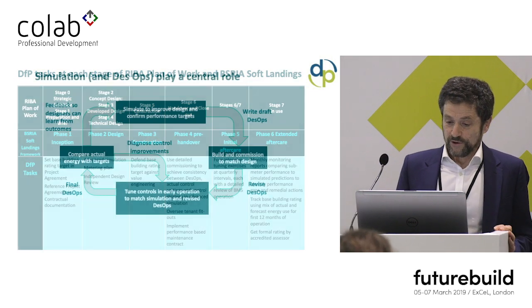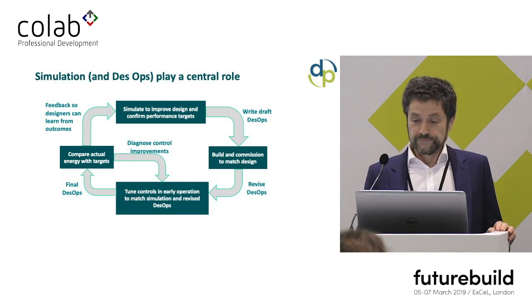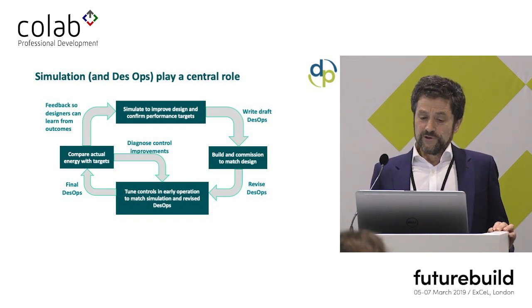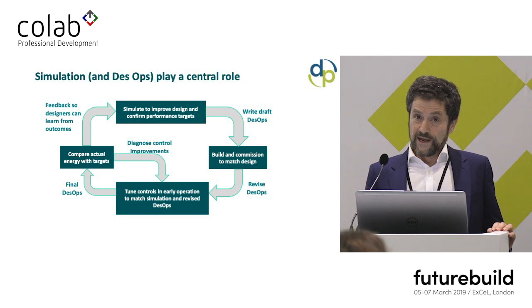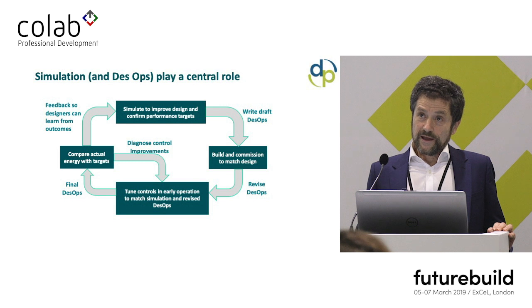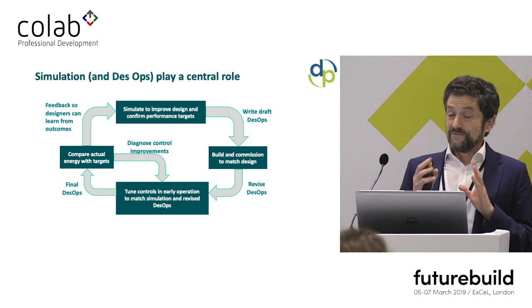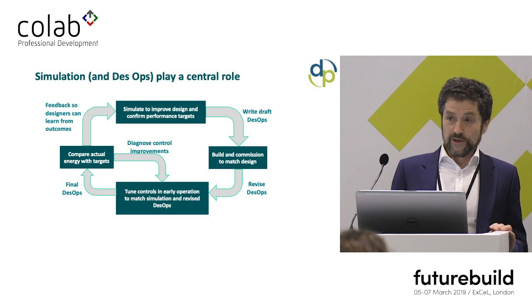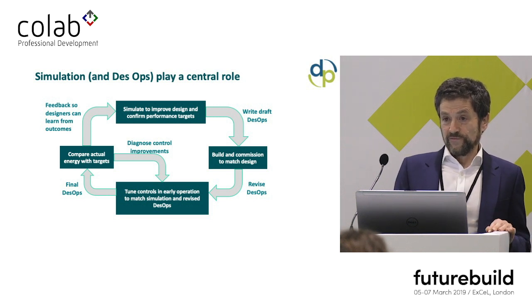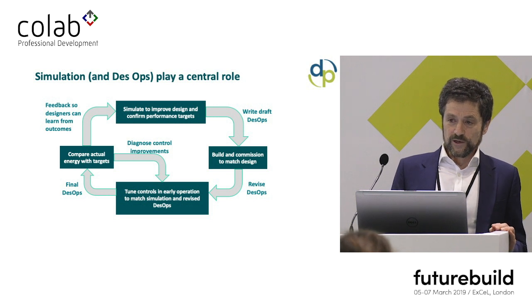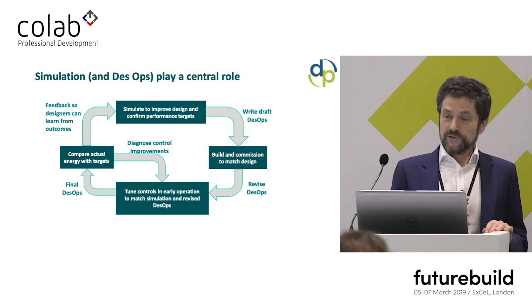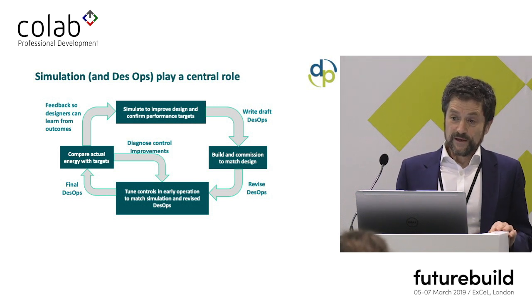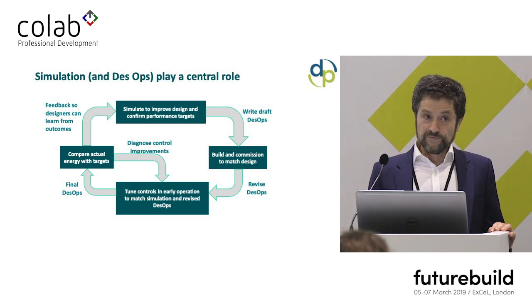I want to focus on the role of advanced simulation. And it's absolutely critical for the building to perform as intended that the HVAC system and its controls are included in the simulation. And that fundamentally is the difference between what they do in Australia in terms of simulation and what we do here. And I'm talking here about level 5 simulation for larger or more complex buildings, where you are using a dynamic model, but you do not put into that model the time-step by time-step performance of individual plant.